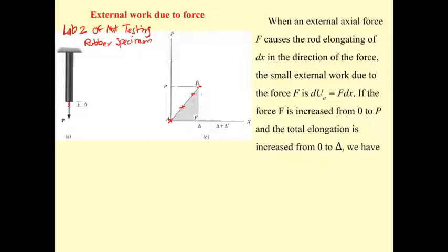So that is going to be 5, this is maybe 8, this is maybe 10 millimeter. So the force that you apply is going to be 50 Newton, 80 Newton. The behavior of the rubber specimen under the lab is linear elastic, so you get the relationship between P and x is linear.